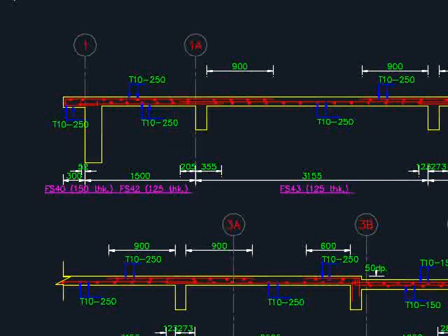When you provide the reinforcement bar, be careful with the main and the secondary reinforcement bar. This is very much dependent on the shape of the slab in terms of the Ly versus Lx. Normally, the reinforcement bar parallel to the Lx will be the main reinforcement bar.